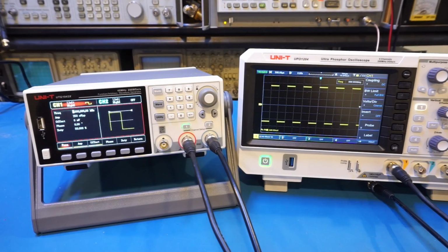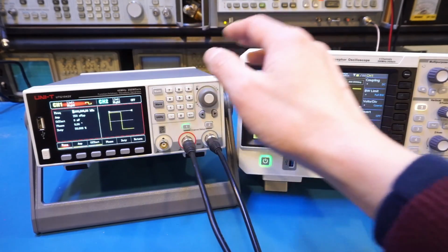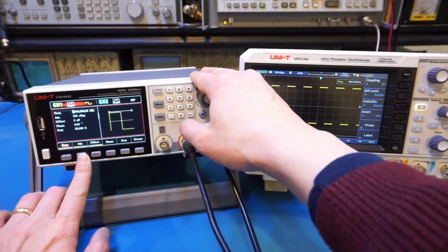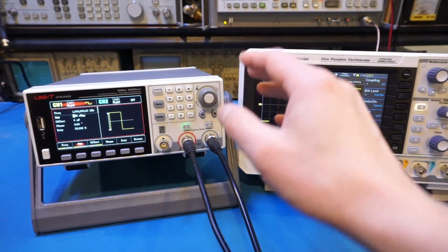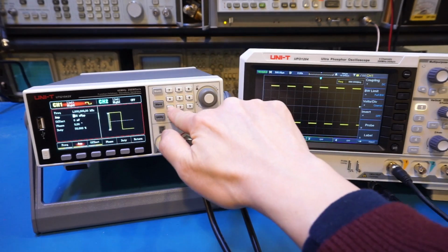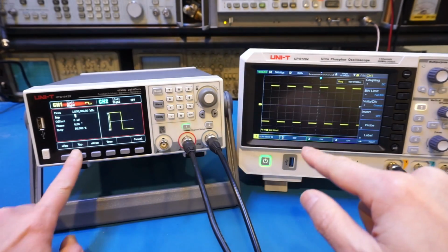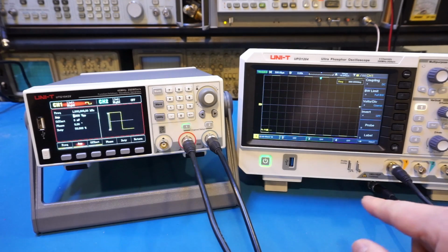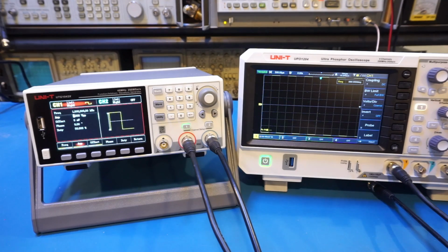While we're measuring the square wave, let's actually take a look at its slew rate. For that, I think I'm going to change the amplitude to 1 volt, so it's easier for us to see, and it's a round number. So let's go to amplitude. And by the way, we have a different way to enter data. Instead of using the rotary encoder, you can also just punch in the data yourself. So for example, 1 volt, and it's very convenient.